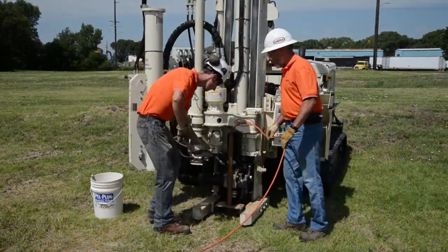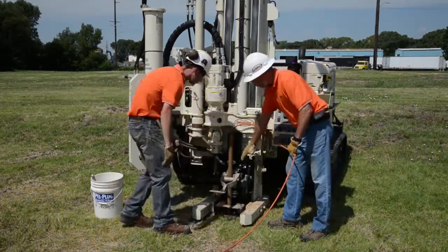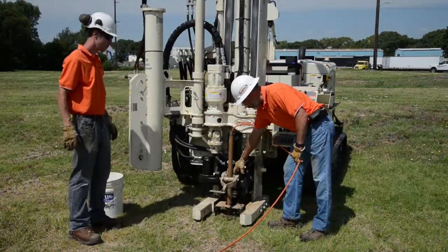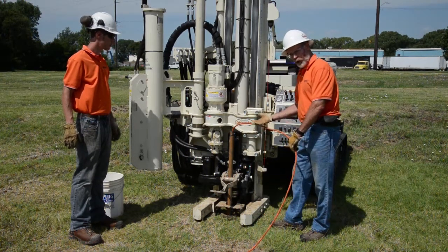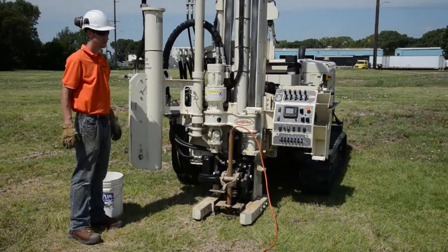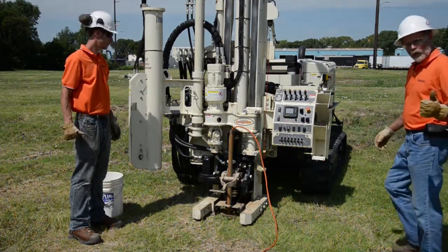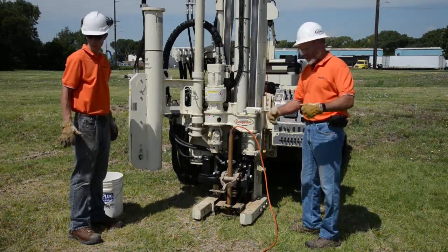Okay, and now we'll put the rod grip handle on, and the rod grip grabs the rod and the jaw on the probe, on the hammer here, and we'll trip the tools out slowly. We've got to make sure we have our HPT flow on. We have flow while we're pulling so we don't clog up the screen with clay or silt.